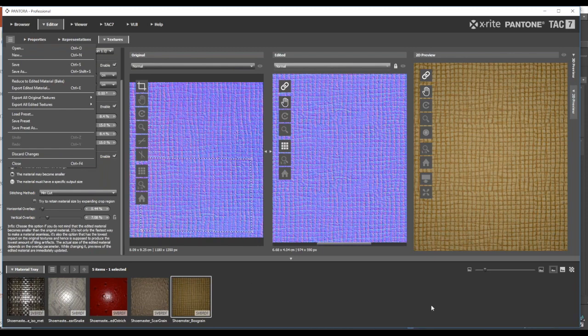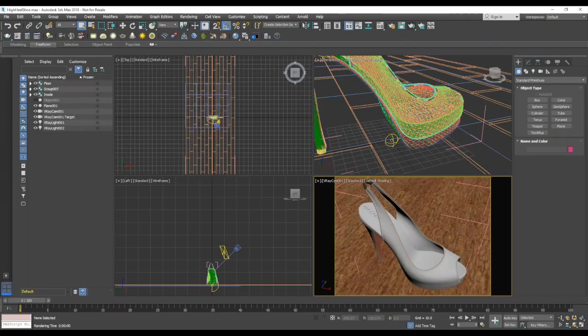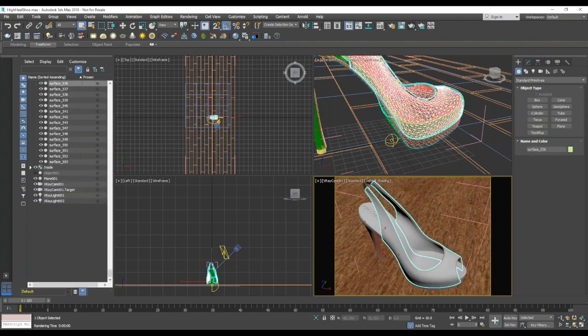So finally, the last portion of this demo will be kind of what this looks like in finality. So if you're using 3ds Max, this just happens to be one CAD application that I have access to. And what we're using here are AxF materials with the V-Ray plugin that we have for that. So the way this would work is you would select your particular material that you're going to modify.